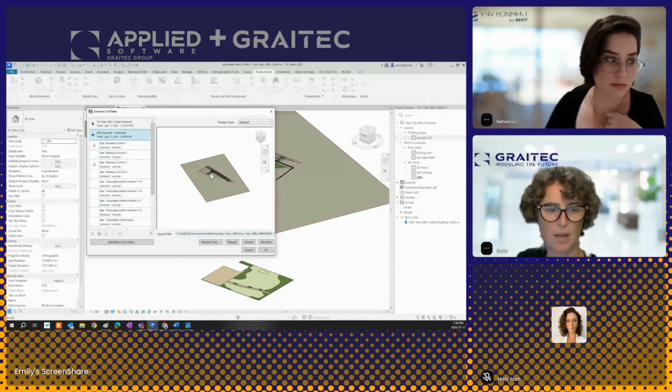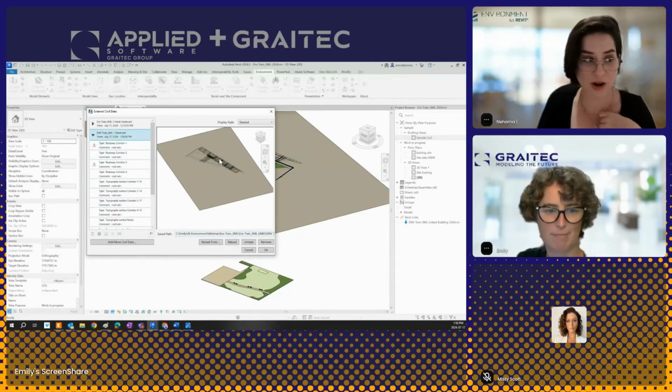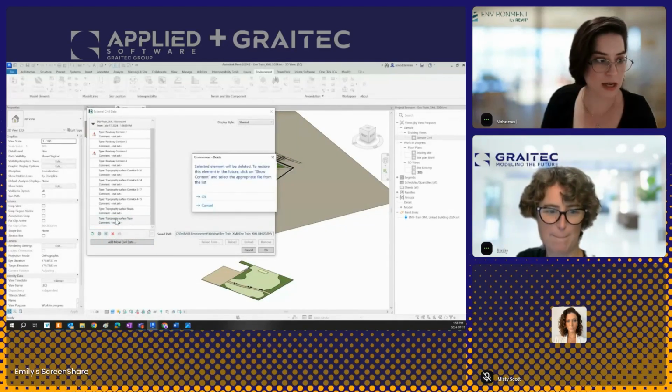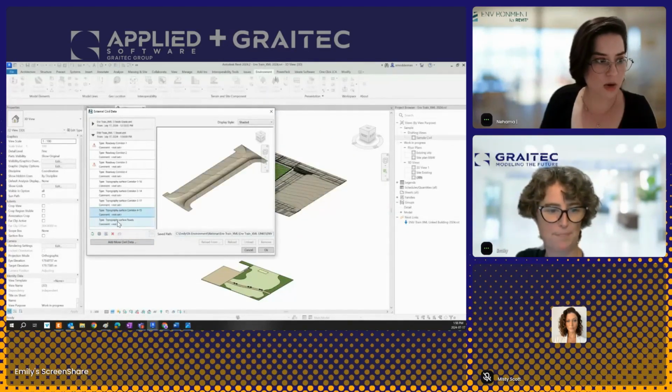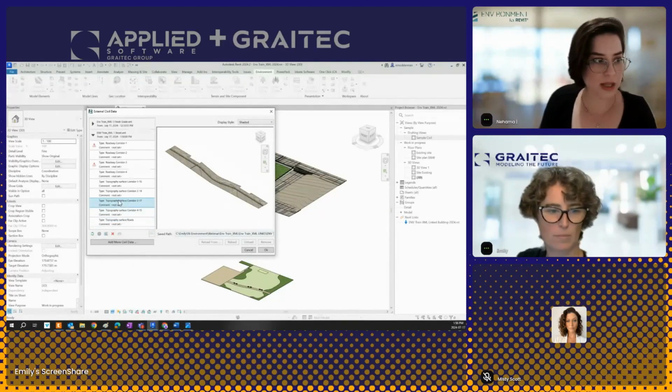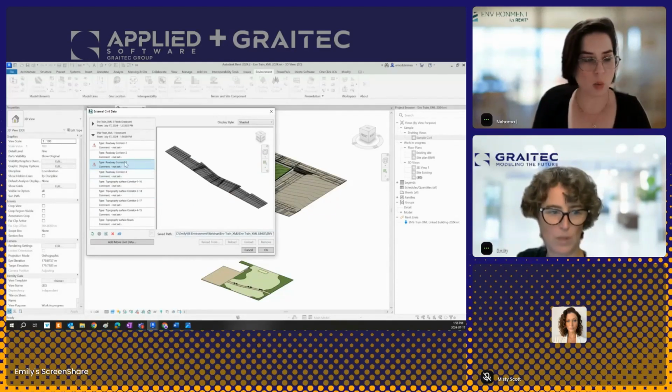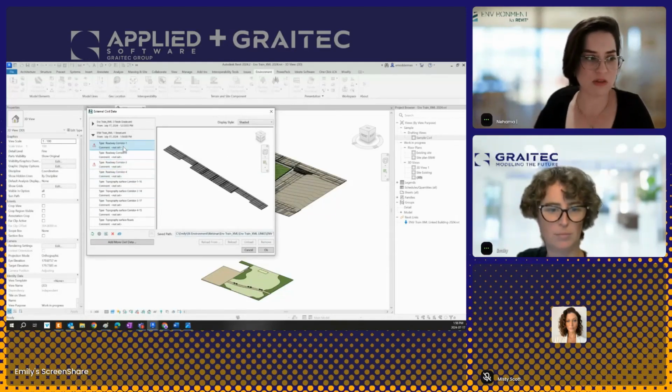And you can see that there's a lot of junk in Civil 3D files, right? So when you're going through this list, Emily, you could just click on the red X at the bottom, and just delete the big topography if you don't need it. So just delete it from your file. The way we build the interface really allows you to clean up the junk, so you can really decide what elements from the Civil 3D file you want to take into your file.